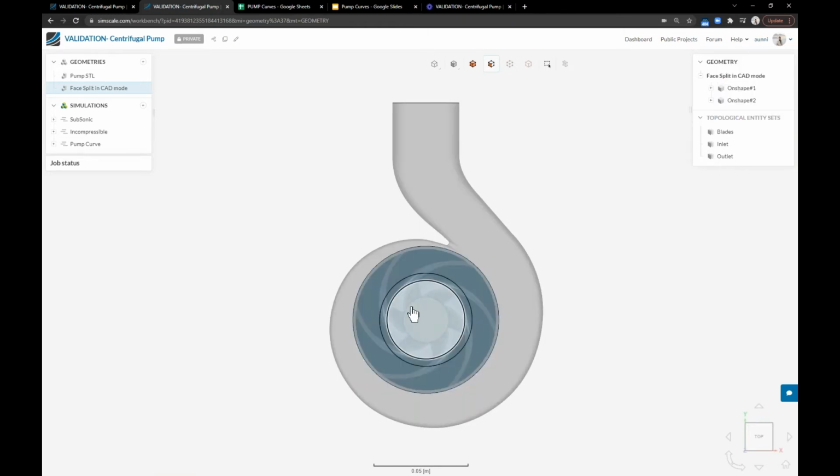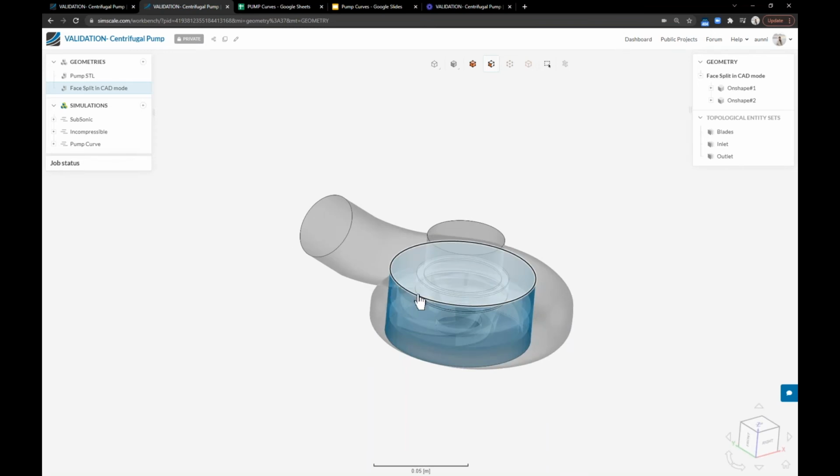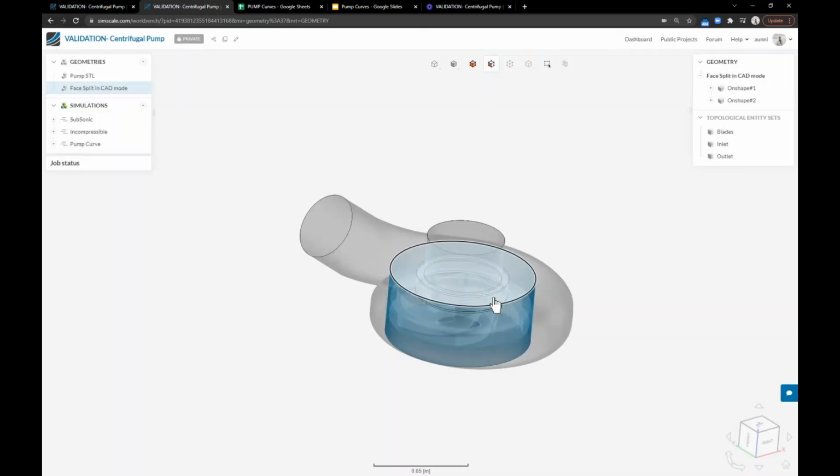So the example I have here is the centrifugal pump that I mentioned. I've got the geometry with the fluid region, and I've also got a cylindrical body around my blades to model the rotation. So step one of setting up any simulation is just getting the CAD, right? On the top left, this is where you can upload different CAD models, and you can upload as many different designs as you want in one go from pretty much any CAD tool out there, just by dragging and dropping it here. Now, once I have the CAD, the setup of the simulation is really straightforward.